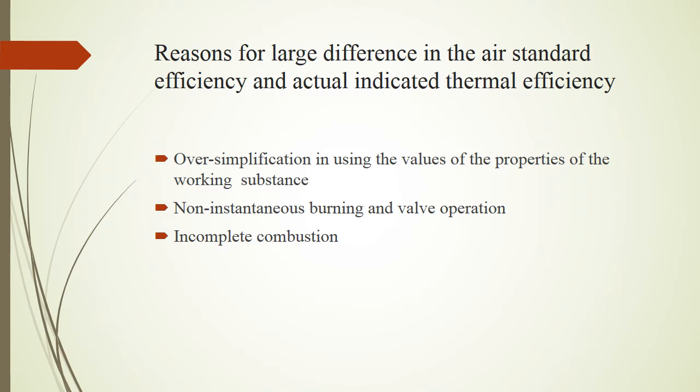Moreover, certain parameters that were assumed, such as the specific heats of the working substance, were oversimplified. Also, in the air standard cycle we assumed combustion to be complete, whereas in the actual engine combustion never completes, and that also results in error in the air standard efficiency.